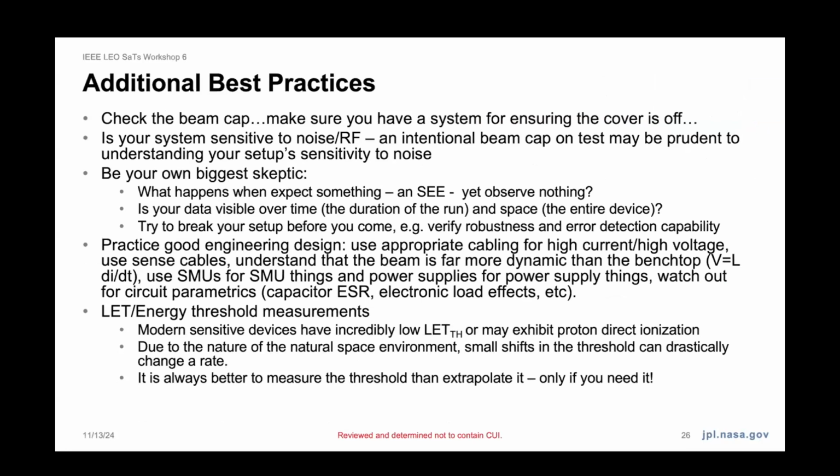And so have redundancy in your team, have a couple people looking for that. You may want to intentionally leave the beam cap on and do a test run of your target while we're blocking the beam. That's because we're in a noisy facility. You may have an impact with RF or noise from the facility, and you want to make sure what you're testing is really due to radiation and not noise in the system.